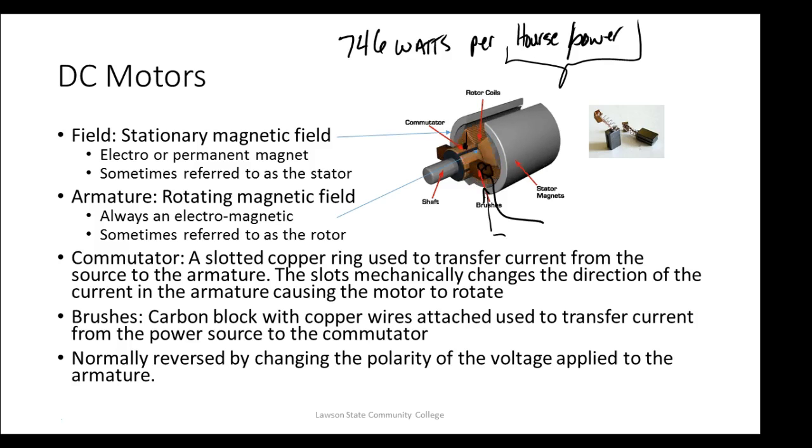So I could sit here with a switch on a DC motor, and every time it stopped, I could flip the switch and change the field, and it would spin around and stop again, right? And if I could get in sync, then of course I could make it spin, but that's going to be highly unlikely. So this commutator automatically does what to the DC motor? It automatically switches it for us. But the problem is, as soon as it does that, I've got to have brushes, right? And then, of course, I got to keep the commutator clean.